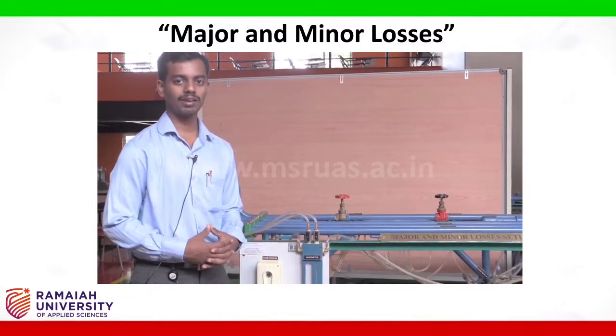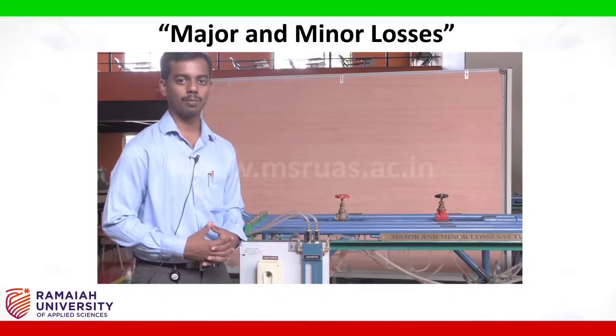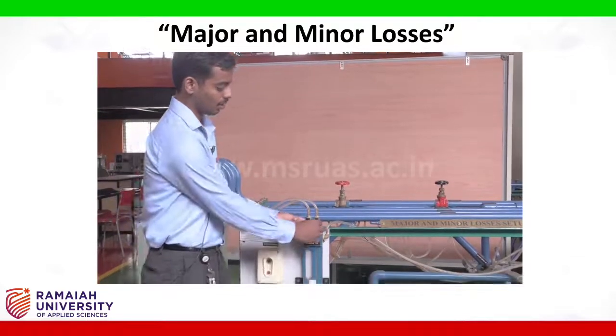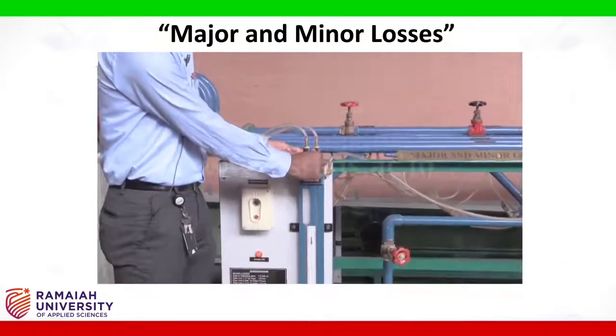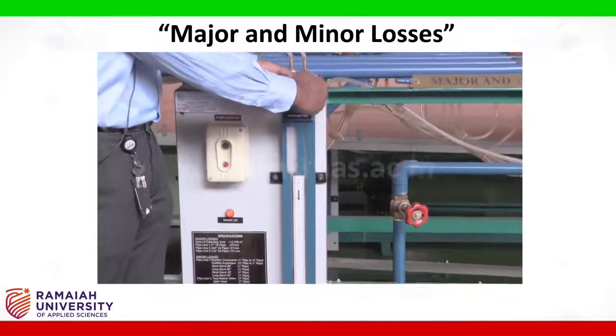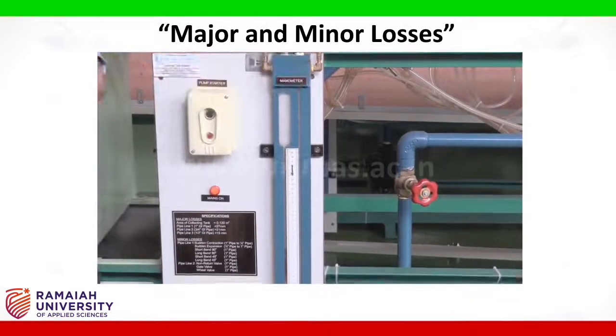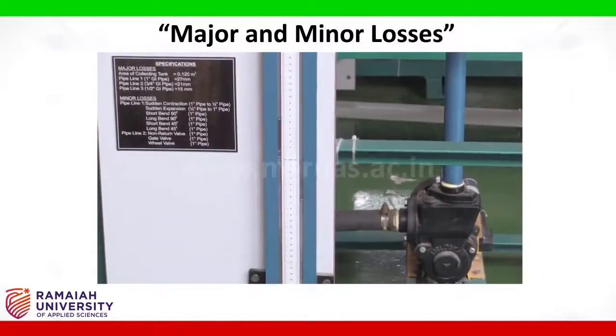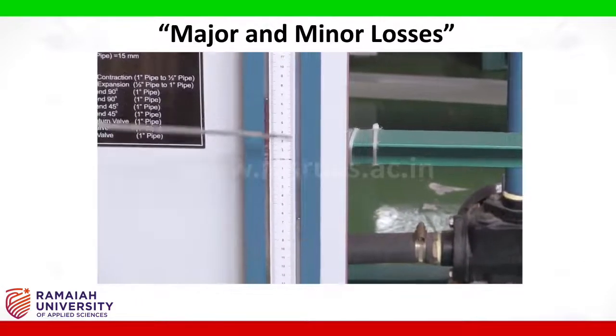In order to calculate the pressure drop across the pipeline, first let us close the valves above the manometer limbs. We shall observe the height difference in the manometer.